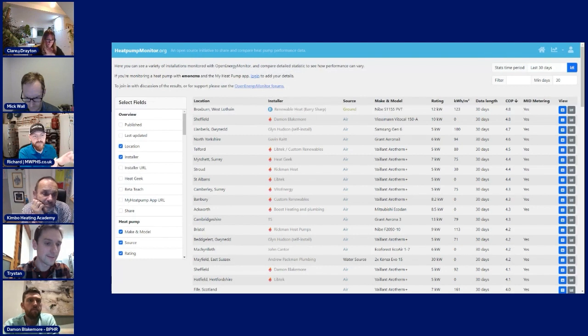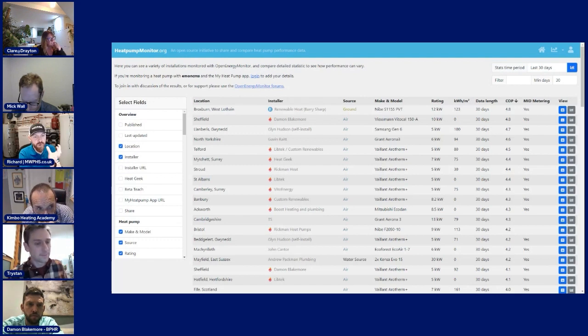And that's some important information that people don't realise. One is obviously that running a coefficient of performance of 4 and above, you're cheaper than gas. Second is obviously that the grams per kilowatt hour of CO2 come massively down as well, because they're divided by the COP. So the electricity used is then multiplied out into heat energy that you get for free from either the ground or the air. So as far as low carbon technology goes, I don't think we're really going to beat heat pumps, are we? I don't think so.